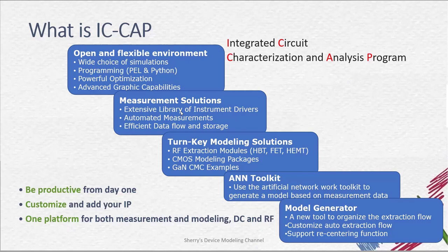It has an extensive library of instrument drivers, and there is a built-in wafer pro with it. You can do automated measurements. And also it has efficient data flow and storage. Besides using the open platform to create your own models, there's also a turnkey modeling solution supported in ICAP. There are RF extraction modules for HBT, FET, and HEMT. There are also CMOS modeling packages, and there are also GaN CMC examples.